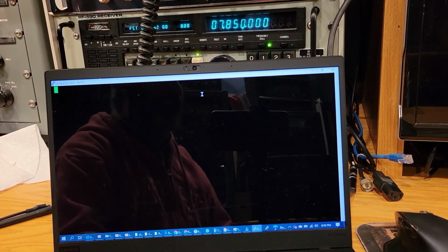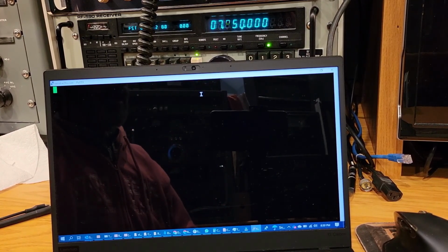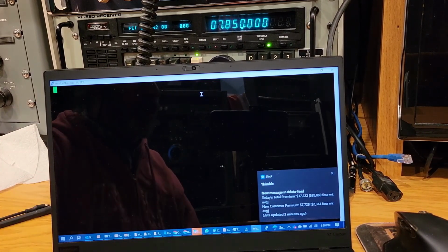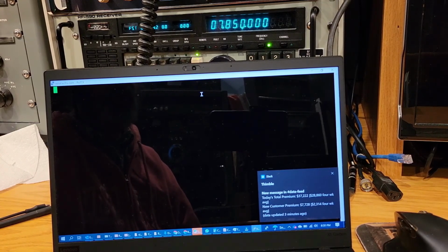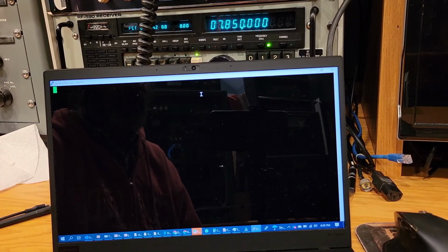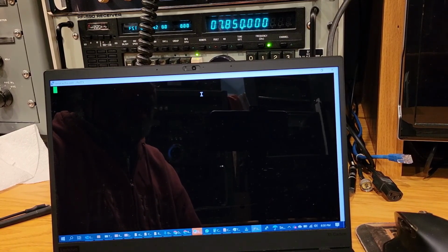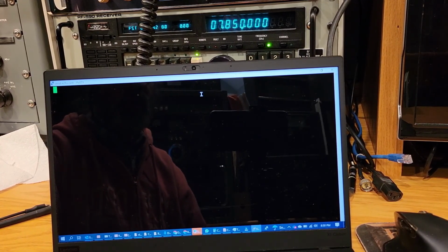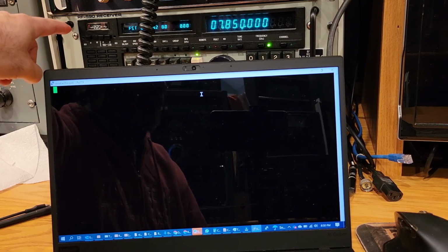All right, I wanted to do one final demonstration, which is putting everything together, which includes using the terminal in addition to this new RTS delay circuit that gives me mark signal between characters, and the fact that I've got the Vox, the voice operated transmit setting, on the exciter and the transmitter set. And so now you can see how the whole thing will work without any manual intervention to go between receive and transmit.